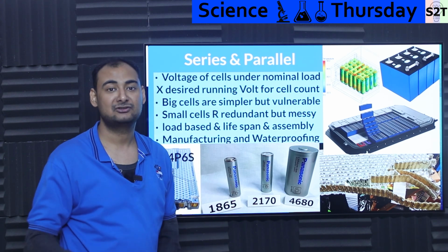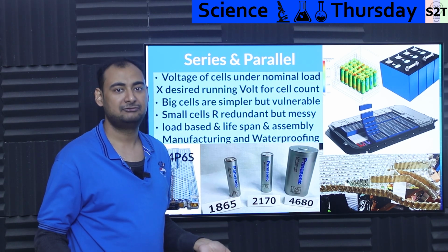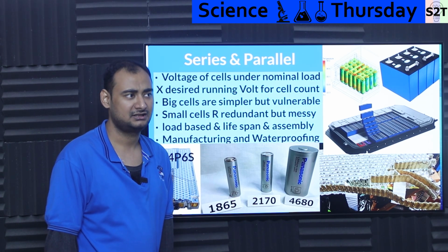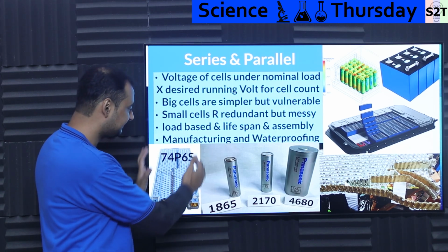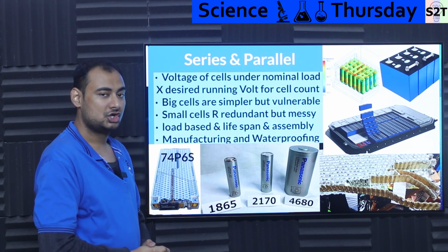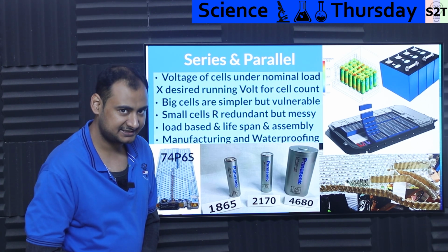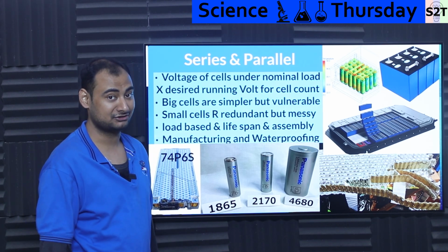He knew that Panasonic was mass producing it. He dealt with them. So it's like, okay, Panasonic could actually fulfill the order. It's like, hey, I need 5,000 cells. Panasonic is like, okay, just give the money, we'll give you that. It's nothing fancy. So he built packs like this. Now, not exactly this pack, but you get the point. And the packs were 74 parallel cells and 6 series. Voltage is not high, capacity is bonkersly high.